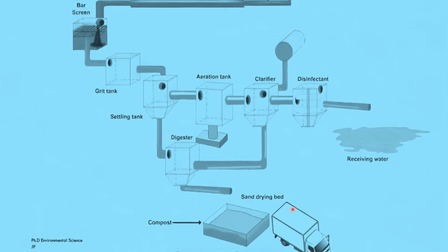In the tertiary treatment process, leftover wastewater is treated with chlorine to remove the phosphorus compounds, nitrogen compounds, and bacteria. It is a chemical process in which chlorine tablets are added to kill the germs, and this process is called chlorination. Then this water is let off into the water bodies.